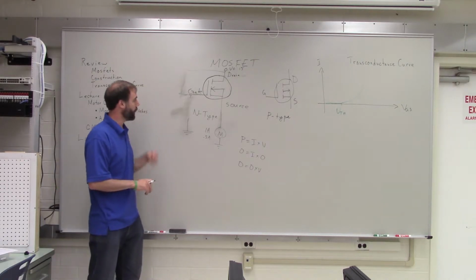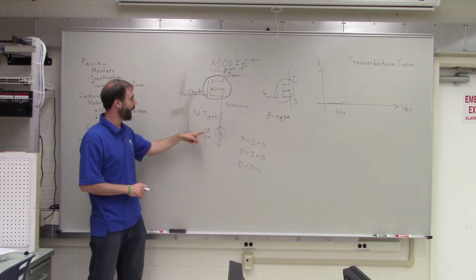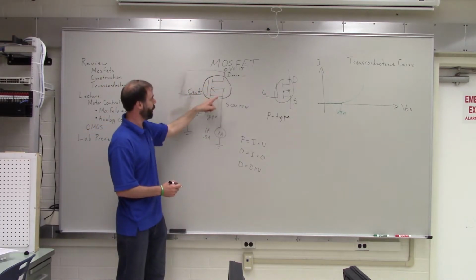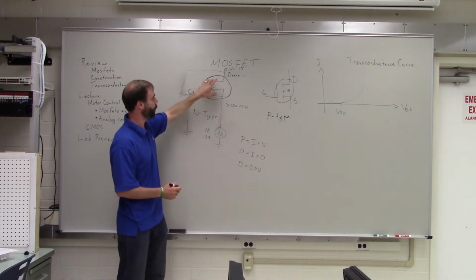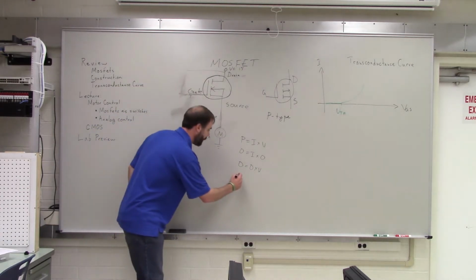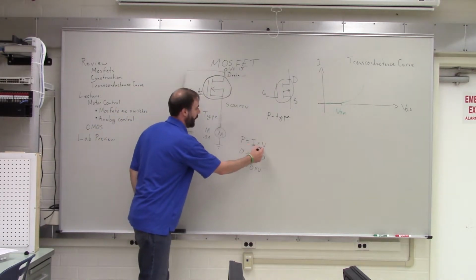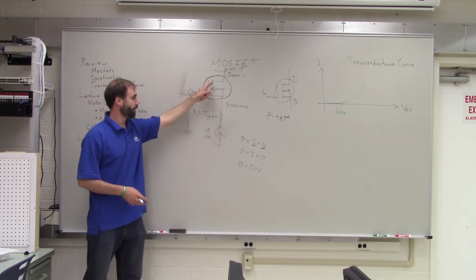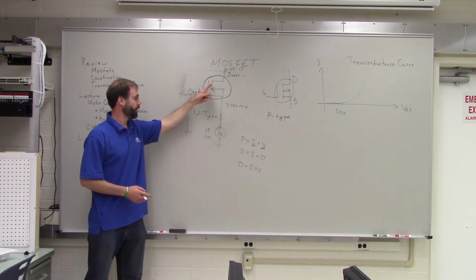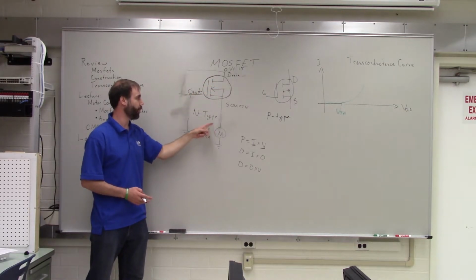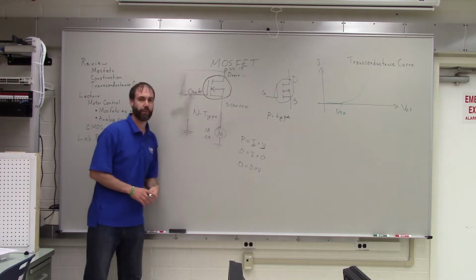The problem is that if you do that, now you've got current flowing through your MOSFET, but you've also got the voltage across your MOSFET. Okay? So now your current and your voltage exist. So basically, the MOSFET is taking a bunch of the energy that should be going to the motor and converting it into heat.